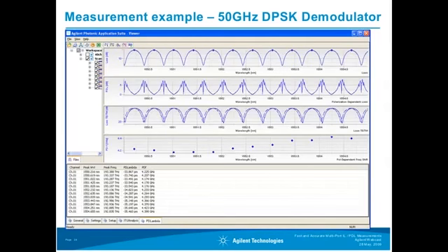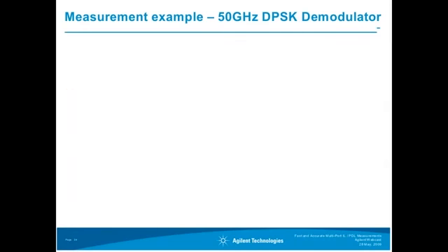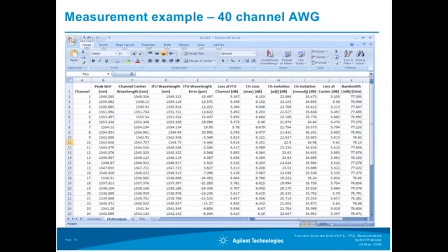And again, in this case, you can export all these data. So you have here the data shown in this analysis table on the bottom. And by a very simple click on the Excel icon here on the top of the screen, you get all the data transferred to Excel, and you immediately have it there for further evaluation. You can also transfer this data to MATLAB or to other programs, or you can just save it as comma-separated values, for example.